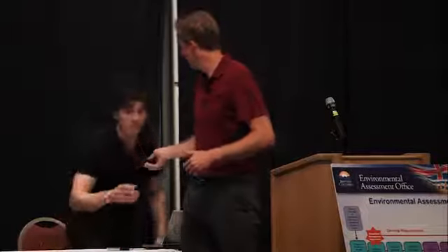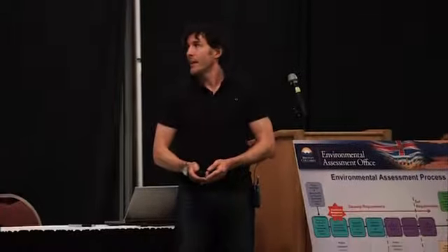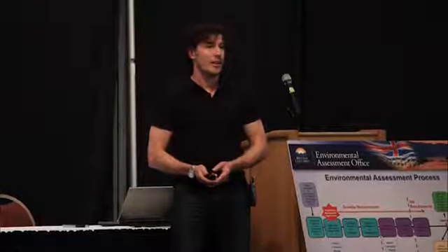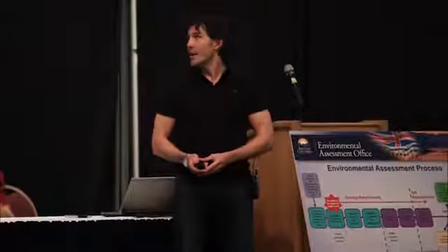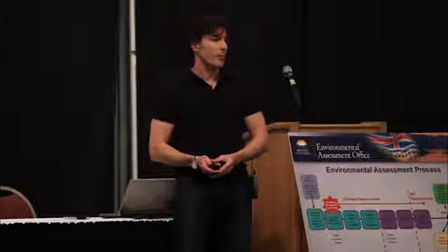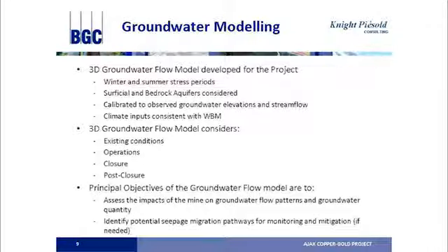Now we'll move on to the groundwater modeling component. So the groundwater model will most likely be developed using a code called MODFLOW that was developed by the US Geological Survey. It's a robust code that's used to develop groundwater flow models in 3 dimensions. It's been benchmarked to a number of case studies, and it's widely used and accepted in this type of study. The model will be developed consistent with the guidelines that are available for us in the province of British Columbia. The Ministry of Environment has put those out just recently.